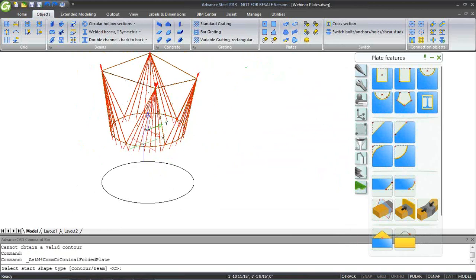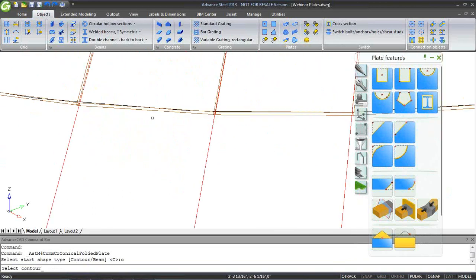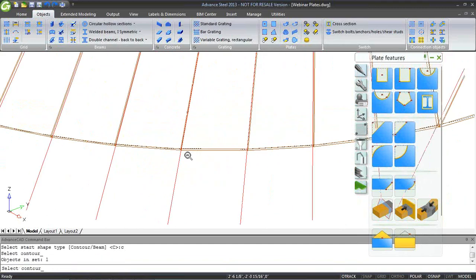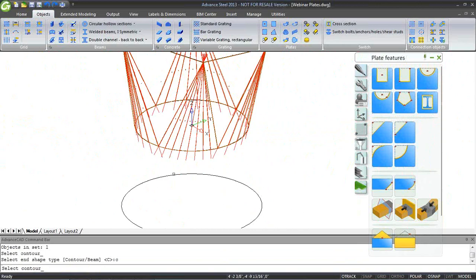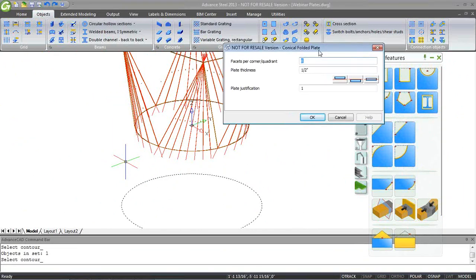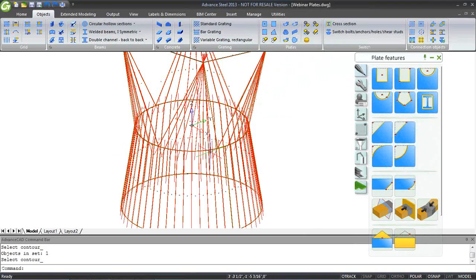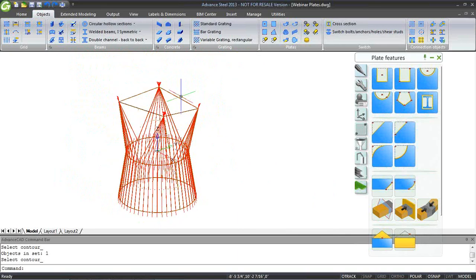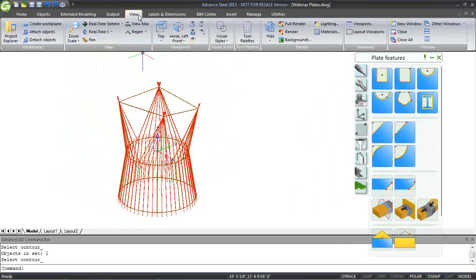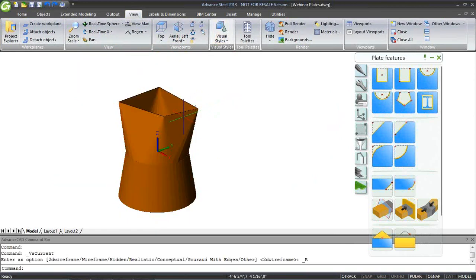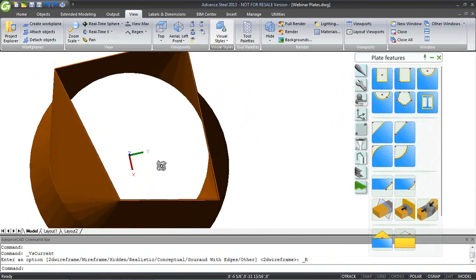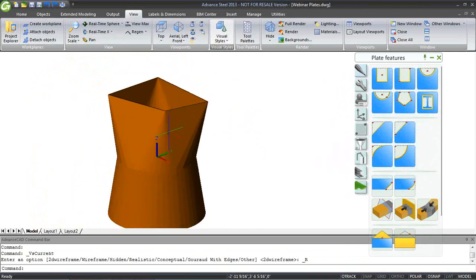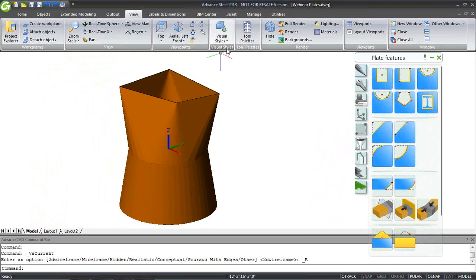Let's do this second operation on those two circles. I'll select this first circle, and the second one at the bottom. Putting more than 8 facets per corner will increase the precision on this plate, so let's put 50. As you can see, all these red lines correspond to bends created on that plate assembly. I'm working now in wireframe. We could change to a more realistic presentation, and all the plates are created upon what we asked on those previous shapes.